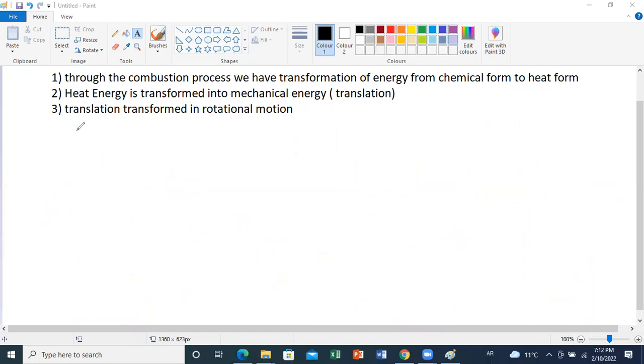So I will say sum of Q dot, where everything in is plus and everything out is minus, equals W dot net. Now let us again draw the cycle and determine at which stage we gain heat, at which stage we reject heat, at which stages we have production of work, and at which stages we need to put work on our system. Going back to our cycle.